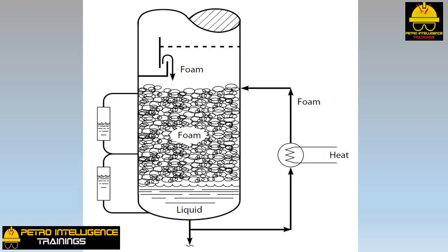This picture shows a distillation tower served by a circulating thermosiphon reboiler. To some unknown extent, some foam will always be found in the bottom of such vessels. Not sometimes, but always. Why? The purpose of a tray is to mix vapor and liquid. This produces aerated liquid or foam. The purpose of a reboiler is to produce vapor. In a circulating reboiler, the reboiler effluent flows up the riser as a froth.